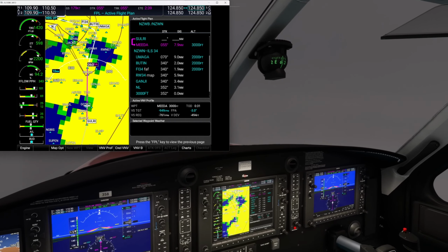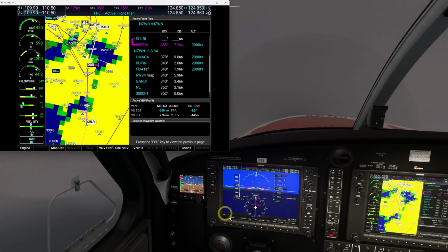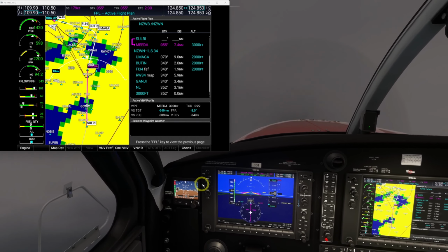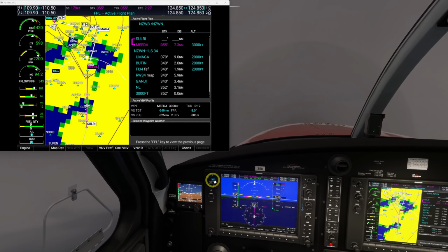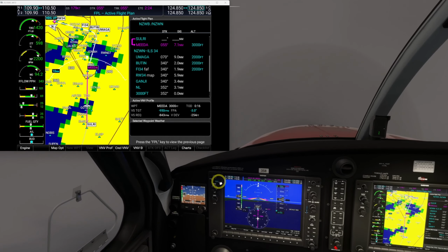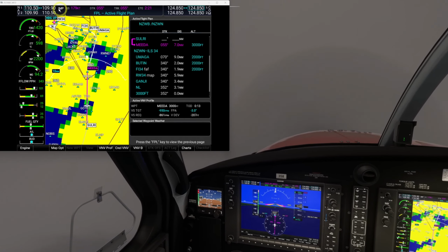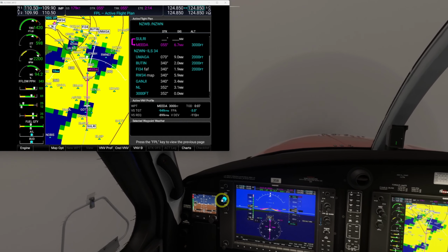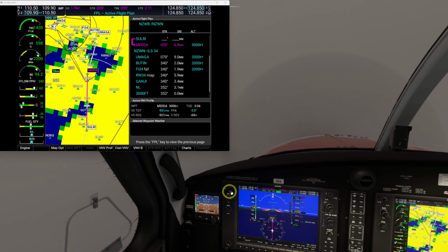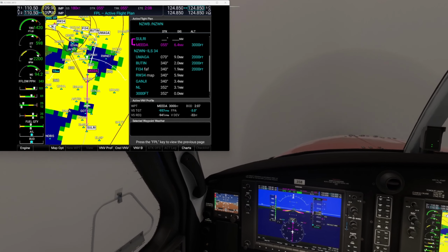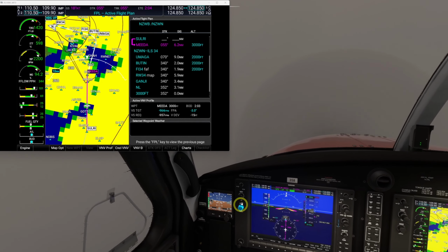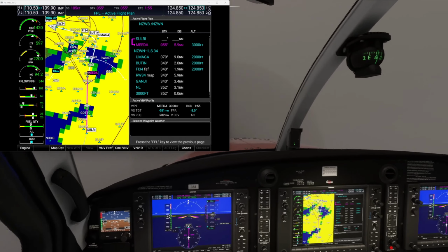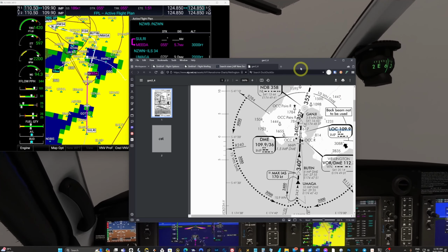And I'm just going to check my localizer 1099. So what I'm going to do now is just come up and right click that nav button there, put it at the top, and hit that 2 arrow there, and now I've got 1099 in nav 1. Now you can put it in nav 2 if you want by just hitting that button there and hitting the double arrow, and you've got them all, but nav 2 is now active, which I don't want, so I'm just going to go back and make sure I've got nav 1 active, 1099 and 1099, just make sure that's correct.